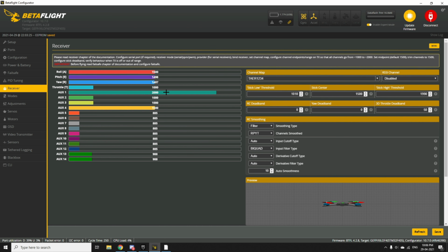There are many videos on YouTube and also FrSky's website on how to bind it. And if you still don't know, you just need to hold down the bind button and put your transmitter in bind mode and connect it. I've already made a video to show what you need to do if both of the lights are green, and both of the green and red lights are solid. You need to change the firmware. You can refer to my previous video for that.